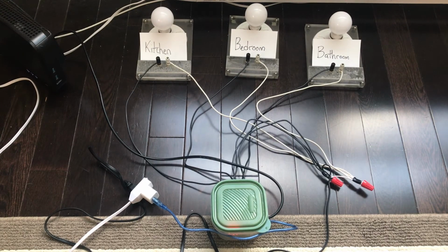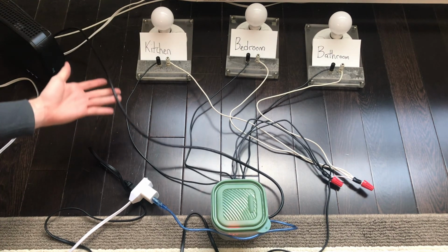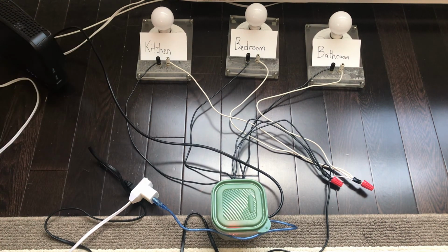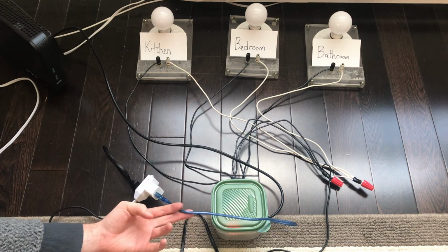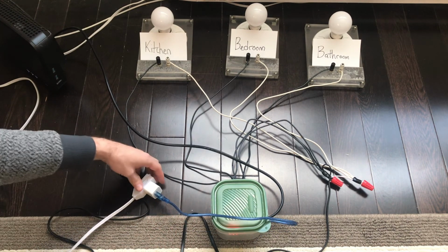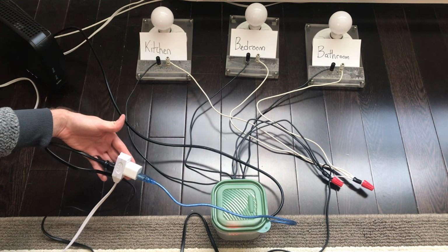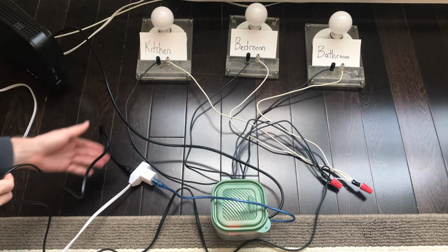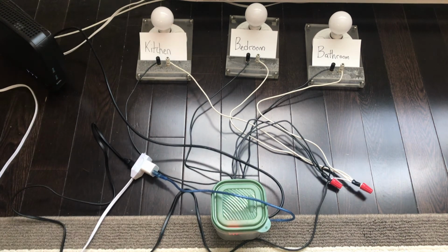The last thing to talk about before we see how the house lighting control system operates is the wiring of the physical components. There are three main wires that make up different power supplies. They are the Ethernet cable running from the Arduino Ethernet shield to the router, the Arduino power supply, which is just the supplied USB connected to an iPhone charging block and plugged into the wall outlet, and lastly is the light power supply. The light power supply is an old cable that was spliced, revealing a neutral and hot wire.